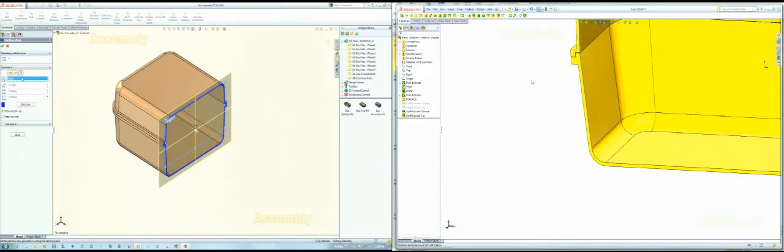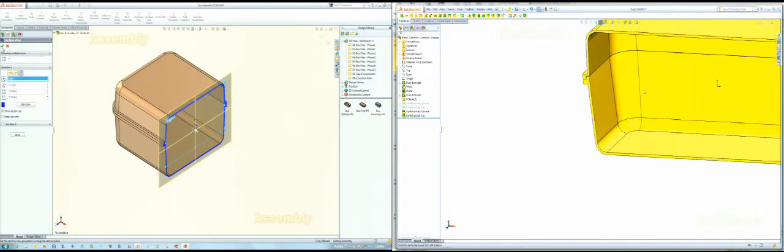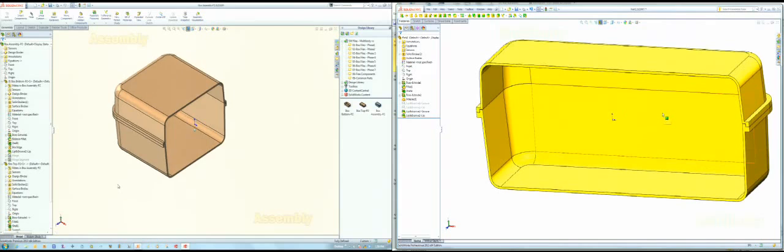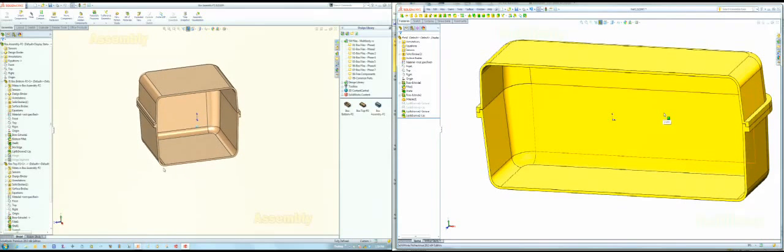Okay, on the assembly side, it's pretty much the same thing. The one difference is we're going to start the lip and groove feature by editing one of the parts. In this case, I had picked the bottom part and said edit part. Pretty much everything else from there was the same as Phil's, except now we have to look at something, because we actually learned something doing this presentation that we hadn't understood before.